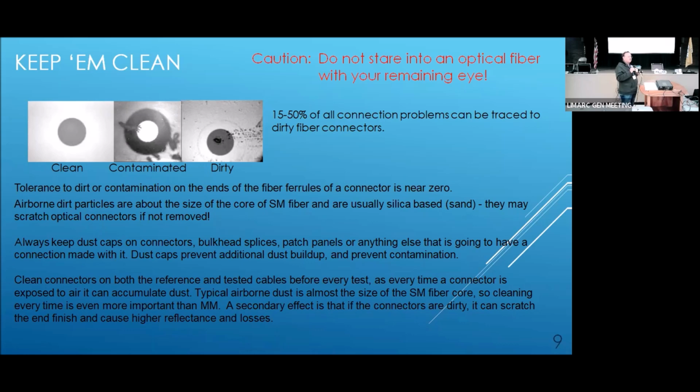If that material is on a laser excited fiber and it gets very dusty, the laser has so much power per square meter. Now keep in mind that the laser may have a couple of milliwatts in it, but in reality, we're not talking about a square meter. We're talking about a nanometer, a really tiny area. There is so much energy in that dust that the dust catches on fire. And it's actually been known to melt fibers and spread because of the fire. So fibers have to be kept pristinely clean in order to work.